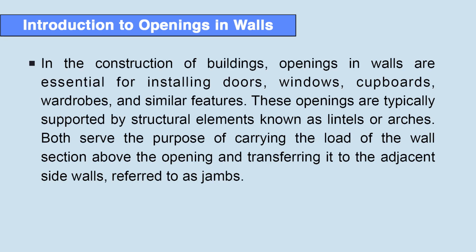In the construction of buildings, openings in the walls are essential for installing doors, windows, cupboards, wardrobes and similar features. These openings are typically supported by structural elements known as lintels or arches. Both serve the purpose of carrying the load of the wall section above the opening and transferring it to the adjacent side wall, which is referred to as jambs.